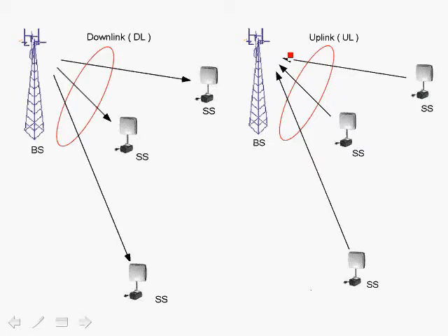That's one of the benefits of OFDM, where the OFDM symbol is created through an inverse FFT process. And because of the cyclic nature, there's actually the guard interval, which is better referred to as the cyclic prefix, allows the transmissions from the subscribers to be in error within that window.